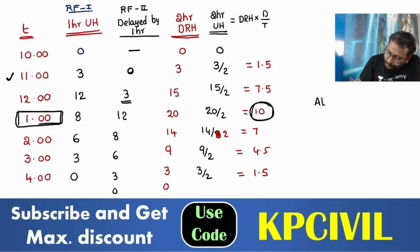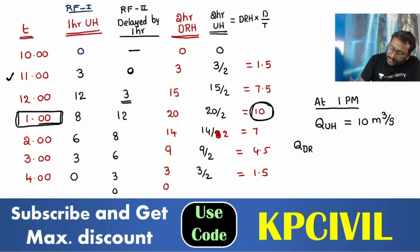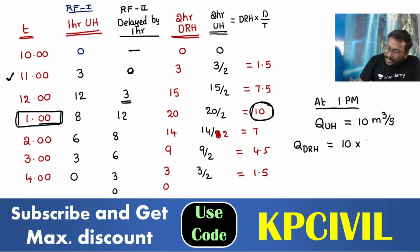At 1 p.m., the unit hydrograph discharge is 10 meter cube per second. Then what is the flood hydrograph? Now, the direct runoff hydrograph discharge at 1 p.m. is the unit hydrograph discharge into effective rainfall. What is the effective rainfall depth? Clearly mentioned, effective rainfall depth is 4 centimeter. So DRH is equal to UH into 4, that is 40.